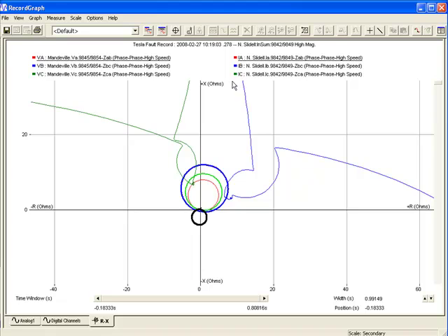In the same way, zone 3 has also been penetrated by my B2C impedance. This is how you plot impedance fault trajectories with your Mho distance relay characteristics settings. I hope this is helpful for you.